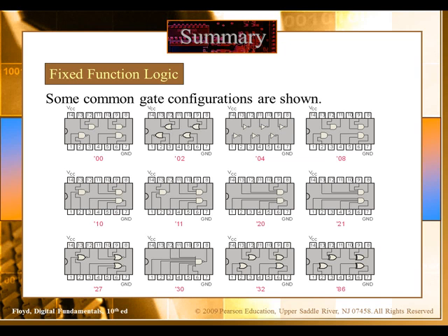But be careful, this is only true for our ICs. There are several ICs in the world that have VCC and the ground not on pin 7 and pin 14. So before you connect those things, you must always check the data sheet, because every IC may be different. Some ICs might have 16 pins, some ICs might have 24 pins.